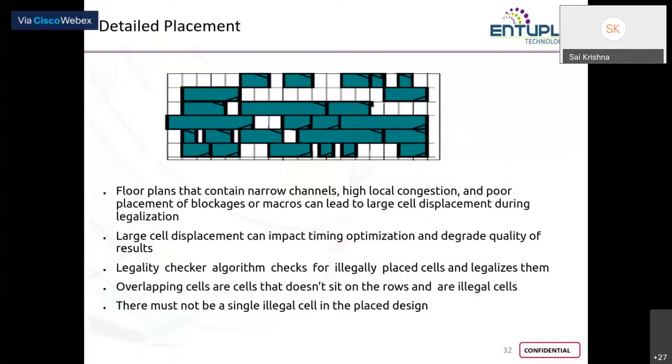Once your congestion is cleared, the second thing that you have to check is your area, power or timing. Area and power, you will probably directly get. Whereas your timing, you will be checking only for setup, because till now we do not have a real propagating clock. So all the clock information for sequential cells is taken only from your SDC.